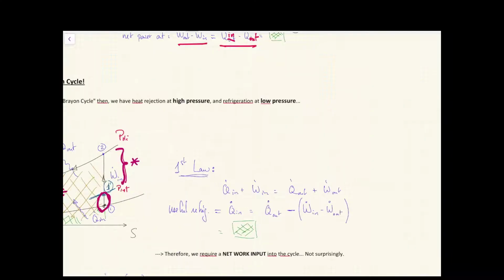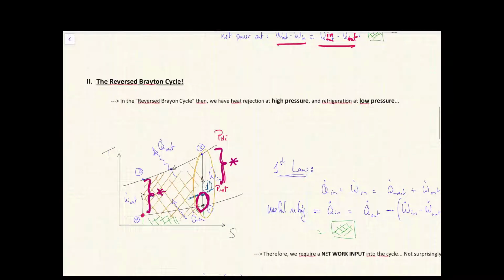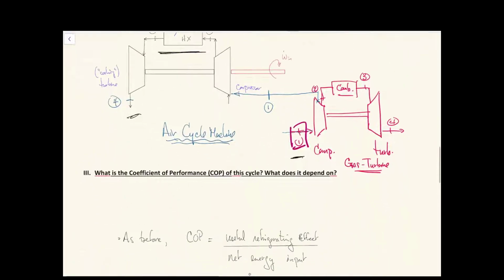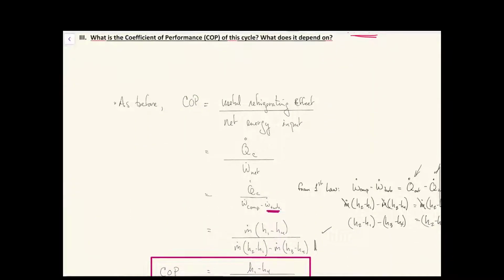These components here are not ideal, meaning that they're not straight lines. They're going to have isentropic efficiencies, which is not unity, and so therefore my cycle is actually going to lean over to the right continuously on both sides, and that's going to cost me. That's going to cost me on COP and ultimately on the amount of air I need to bleed out of the main engine. Always a bad thing.